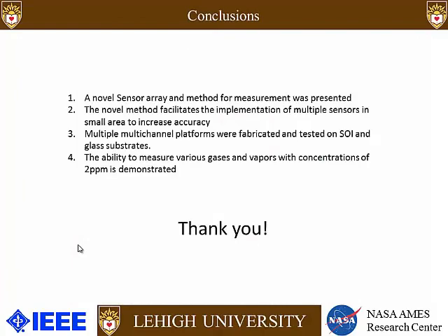And to conclude, we have created a novel sensor array and method for measurement with carbon nanotubes, including PIN sensors. The novel method facilitates the implementation of multiple sensors in a small area to increase the accuracy. The multiple channel platforms were fabricated and tested on SOI and glass substrates. And the ability to measure various gases and vapors with a concentration of 2 parts per million was demonstrated here.